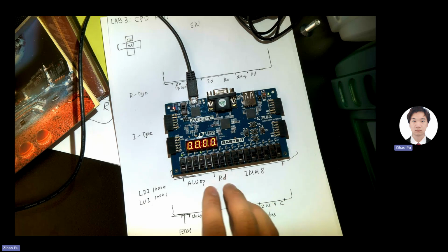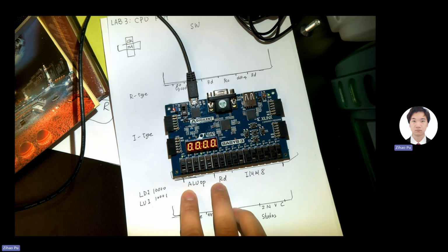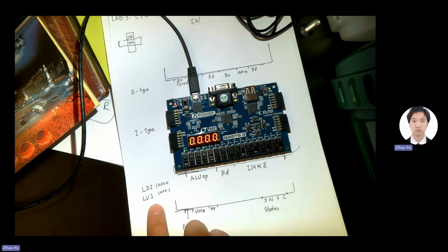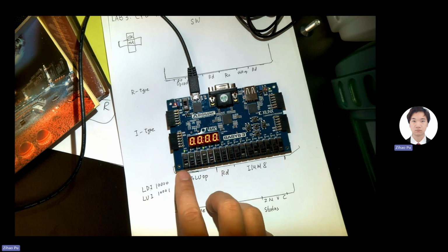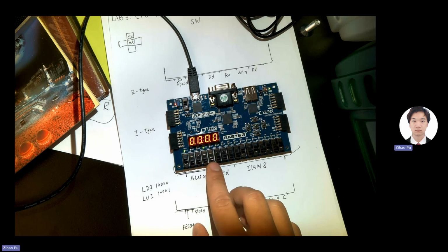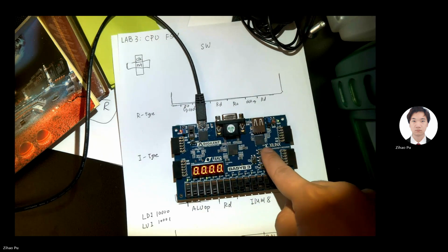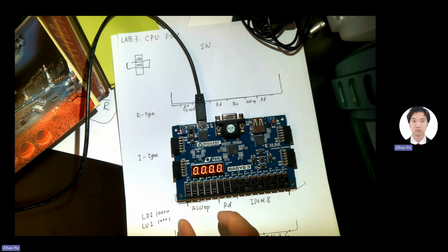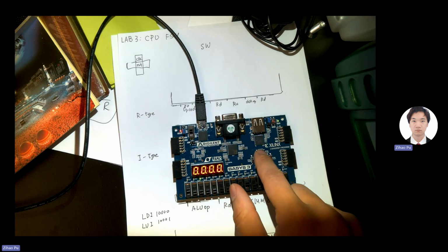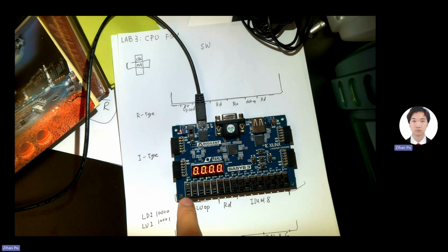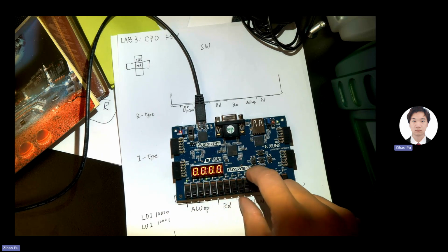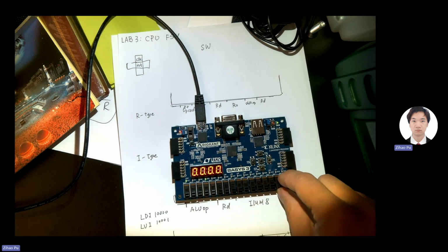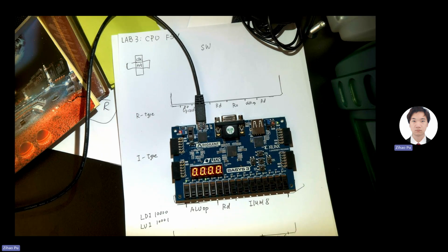And now we have the ALU OP, which is the opcode for the instruction. For LDI, which is lower 8 bits, I will just leave it to be 10000. Now I'm going to use the clock to run it. So you can see the state changes here, and I give another one. Okay, you see the fetch LED is on again. That means this instruction is successfully finished, executed, and I'm going to give it another instruction.